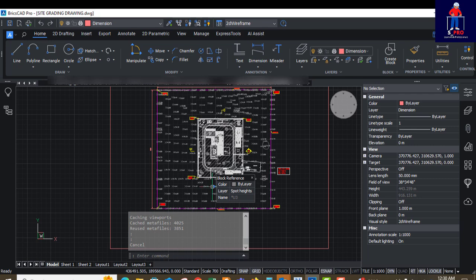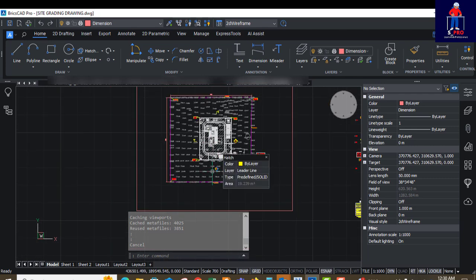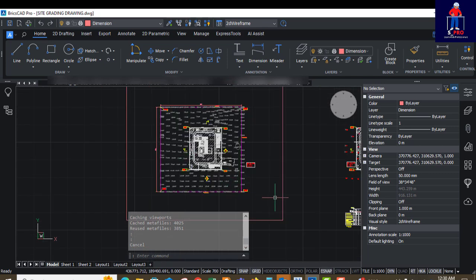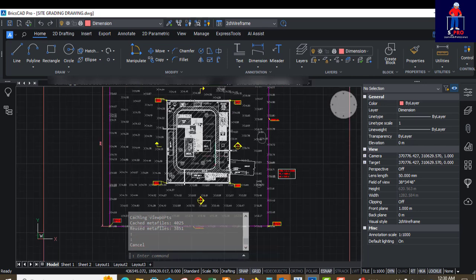So if you are going for this kind of site visit, you need to prepare a checklist. Inside the checklist you are going to put, number one, to check the accessibility of the plan. Does it have access to road? Okay, if the answer is yes, does the access road have drainage? Because it is going to be very, very important for us to be able to channel our drain water. If it doesn't have drainage, is there any possible drainage outfall?